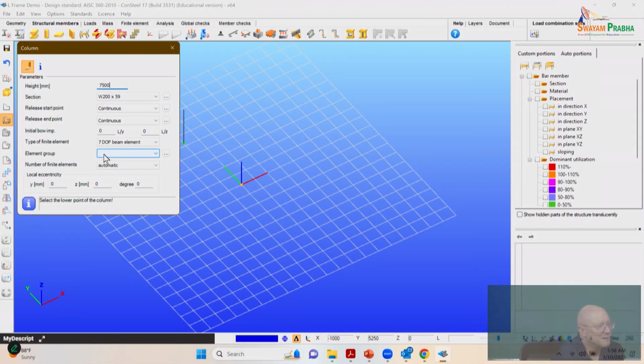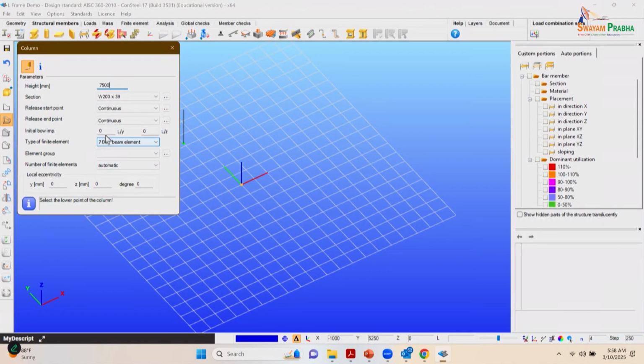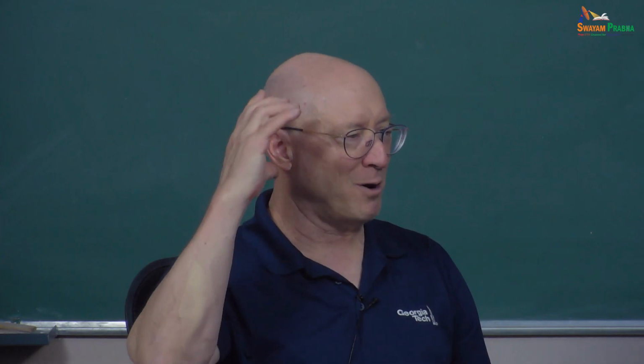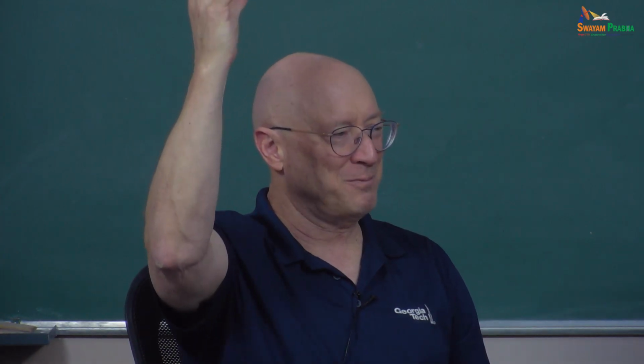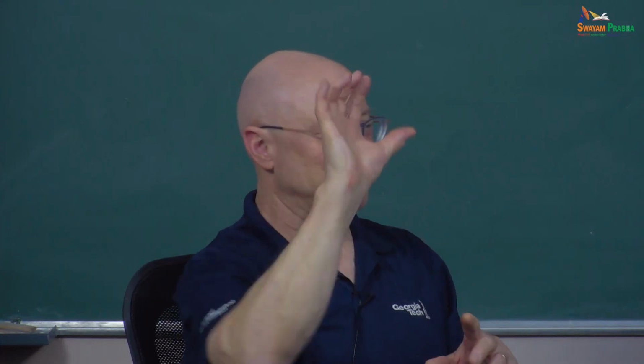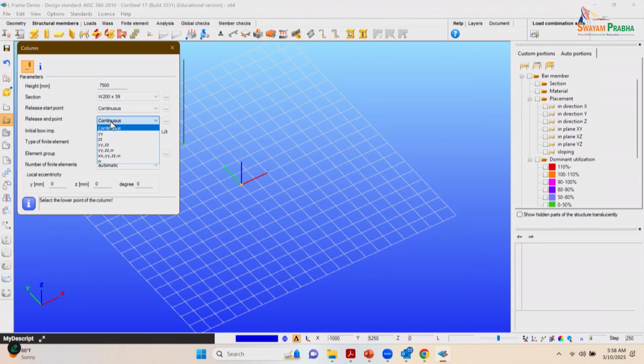So, say it again. The release point, mm-hmm. I saw something called W. If you drop down the continuous thing, okay, it's an XX, YY. Okay, now we're getting into releases. Let's say you want to put in a model that's a perfect spherical joint, bearing joint, and so then you would release XX, YY, ZZ, and so now it's free rotation there. There's also something called W there. W means you're also releasing the warping.